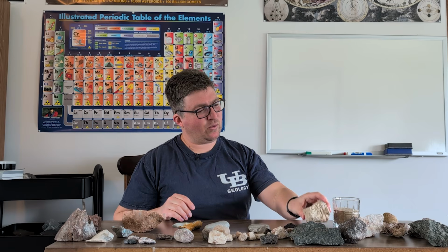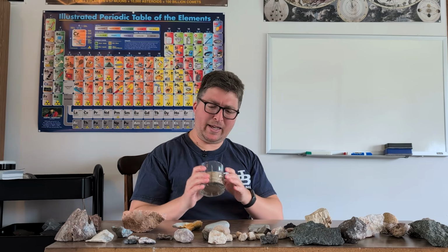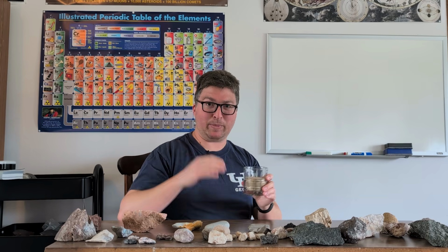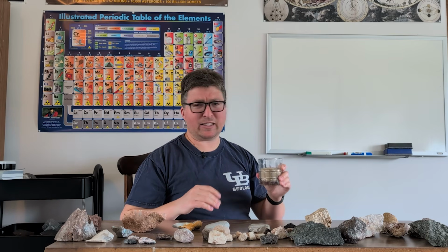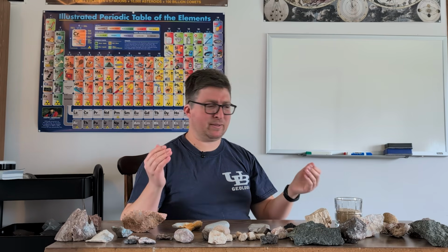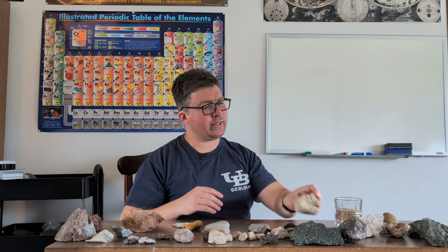Let's look at a few examples of that. We have, well, let's begin with the sand here. Sand has a lot of pore space in it. I mean, you can see this thing's just wiggling around here, so it can bounce around pretty easily. It becomes a little bit like a fluid when you wiggle it, and that's because of all the pore space that's in there. And it's also very permeable. Those pore spaces are connected very easily, very loosely, and water can flow between them pretty easily.